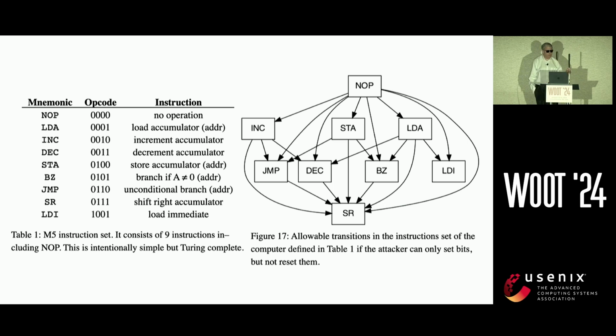It's easy, for example, to redirect a memory access up into high memory. Just set the high bit of the address. So our attacker patiently watches the instruction stream go by on the bus, picking and choosing opcodes that he can alter into the instructions that he wants, slowly building up the desired program in high memory. Maybe it's not quite the program he wanted because certain bit patterns are unreachable. So the first thing the arbitrary-ish code does is run fix-ups on itself. Finally, we redirect a branch to the fixed-up code, and it's game over.